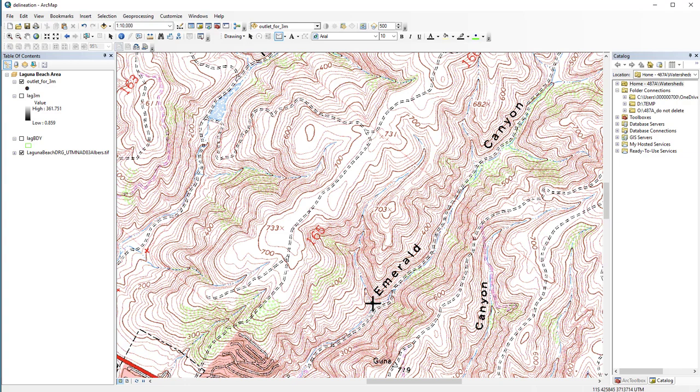So we are going to start at this outlet, and I'm going to just use my eye and my mouse to connect the dots. And I'm clicking along what I think is the ridge line as best as possible. So I'm going to use the vertices. And then when you get to this point right here, you see, if you ever have a benchmark, this is 703 indicates a benchmark. So I'm going to click on that X to make sure that that's included. A benchmark means that it's a measured point on your map and it's the highest point in the map.